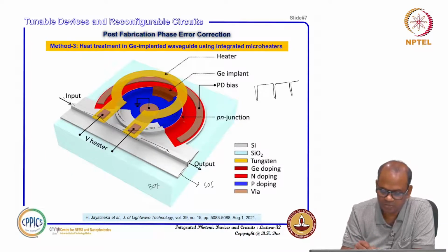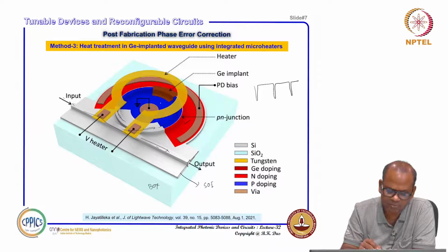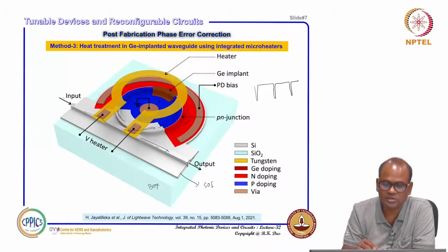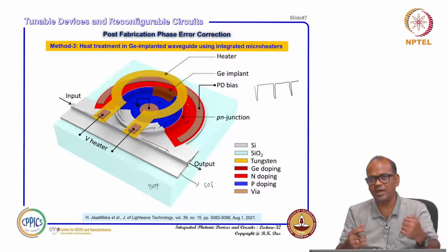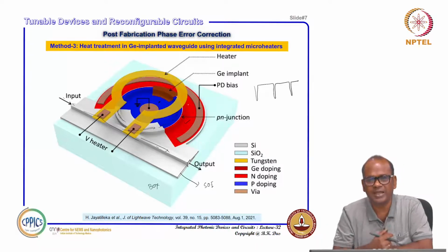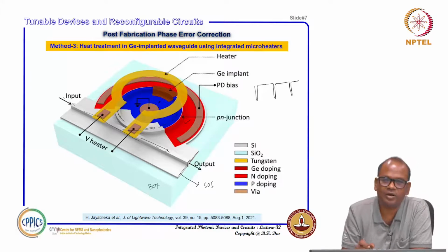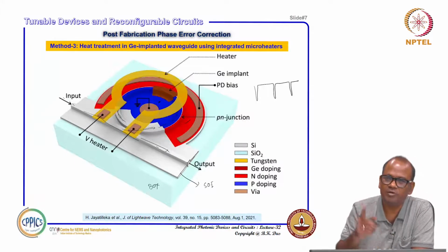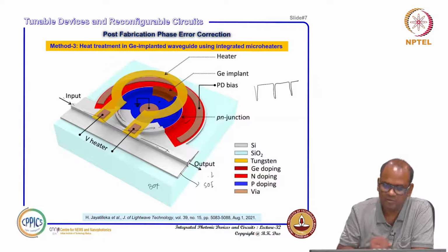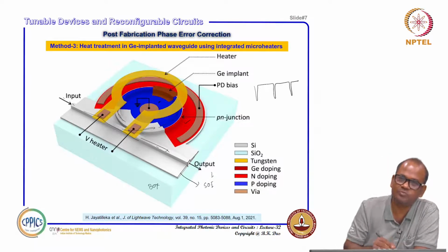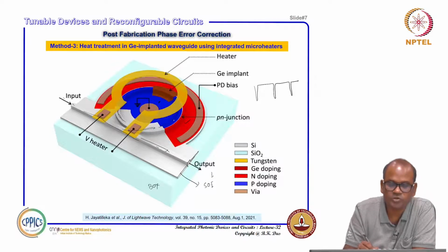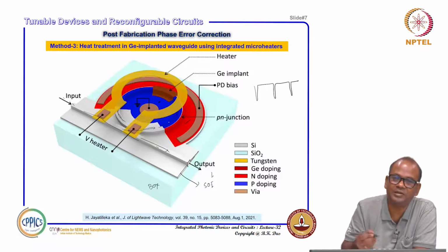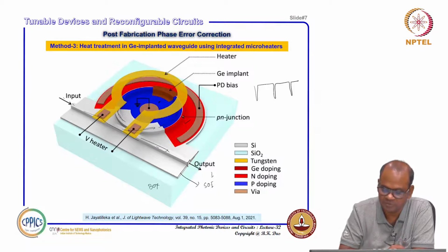What you do is, one side will be p-type doping and the other side, the blue region, maybe n-type doping. So a p-n junction is created across the waveguide. Depending on the bias control, you can actively modulate the refractive index. Once you modulate the refractive index, your resonance can be detuned, and you can have an intensity modulation at the output here. So that's the modulator. I will discuss more details in future classes, but for the moment, just consider that the same device is used for monitoring how much refractive index change has already happened. Okay, how that is used, I will discuss.